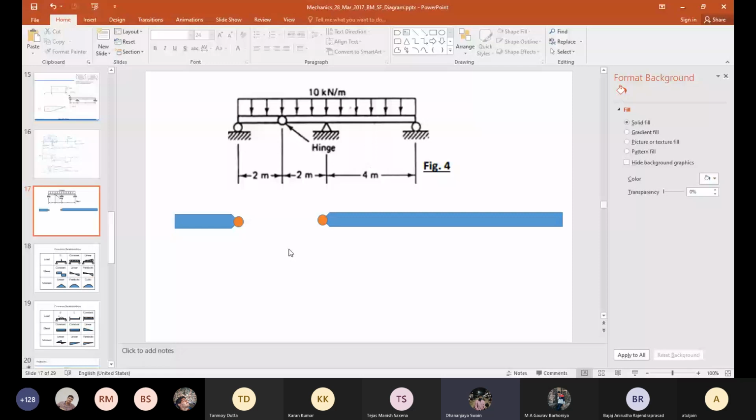Sir, I'm saying that the hinge force is not accounted now because we are not separating the two bodies. There are 3 unknowns, but all the forces are parallel, so you can only calculate for 2 unknowns. So break it into 2 and then you can solve it. It should not be a problem.